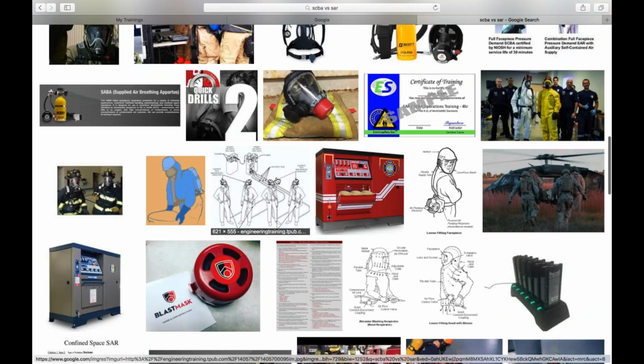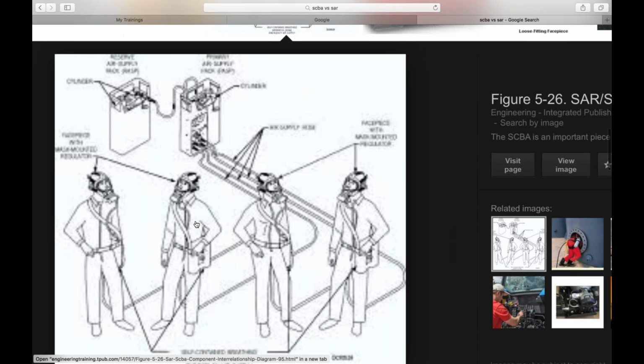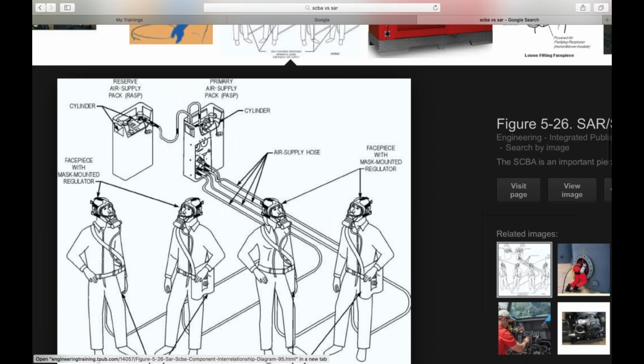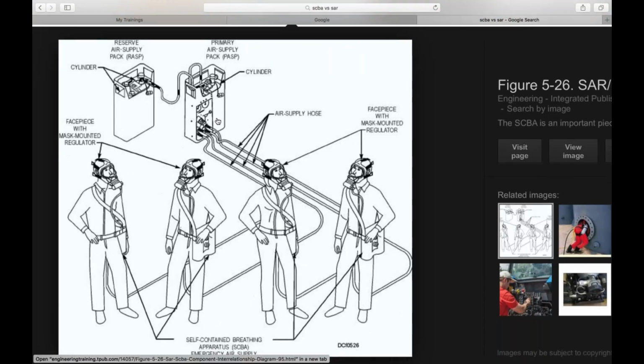And then, of course, you have air supplied respirator, which is something like this, where we're all coming off of either equipment or air packs, fresh air packs. Okay, not oxygen, fresh air, right? Which is going to give us 20.8% oxygen, 78.1% nitrogen, and 1.1% everything else. And these employees are all coming in. As you notice, each one of them has their own airline.